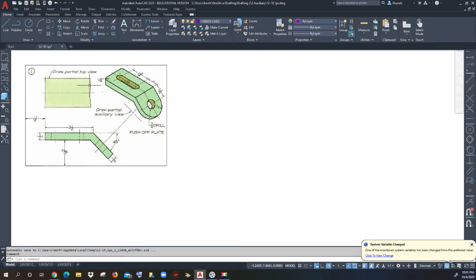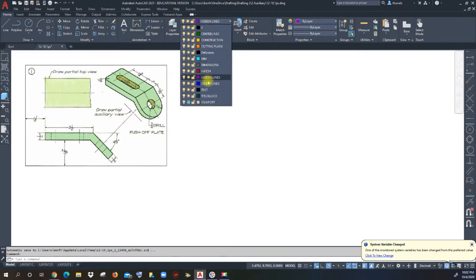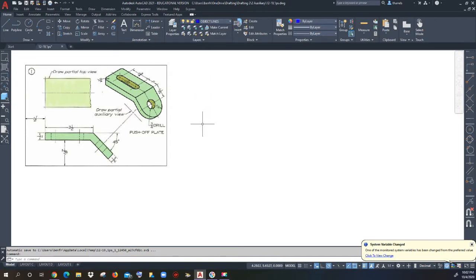So we can use a break line and break that view, so all of this area that would normally have to be projected doesn't have to be. With this part, these dimensions on the side, you can ignore these. When we would do this inside a title block, you didn't have to do a formula anymore. It would actually let you know what your offsets were in order to start the part. So now that you do not have to do a formula and you are in a Paperspace Model Space title block, you can just start to draw.